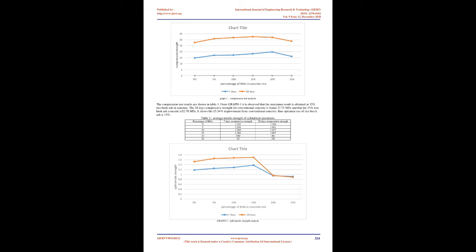4.3 Curing. The sample specimens are set aside within 2 to 3 hours of casting and are kept in a vibration-free place, in almost 90% relative humidity air and at a temperature of 27 plus or minus 2 degrees C for 24 plus or minus 1/2 hours. After this period, the specimens are put in submerged condition in fresh water in a tank and are kept there until testing. The duration of curing of samples is according to their schedule of testing.